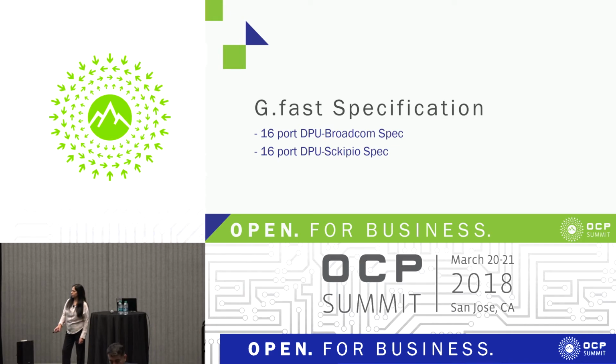In the first generation, we're getting, I wouldn't say 1 gig, but it's close. You can do up to like 500 to 750 meg service. And with the second gen G.fast, it goes all the way to 1 gig symmetric service or an aggregate of 1.5 gig. So it's pretty good, comparable service to fiber.